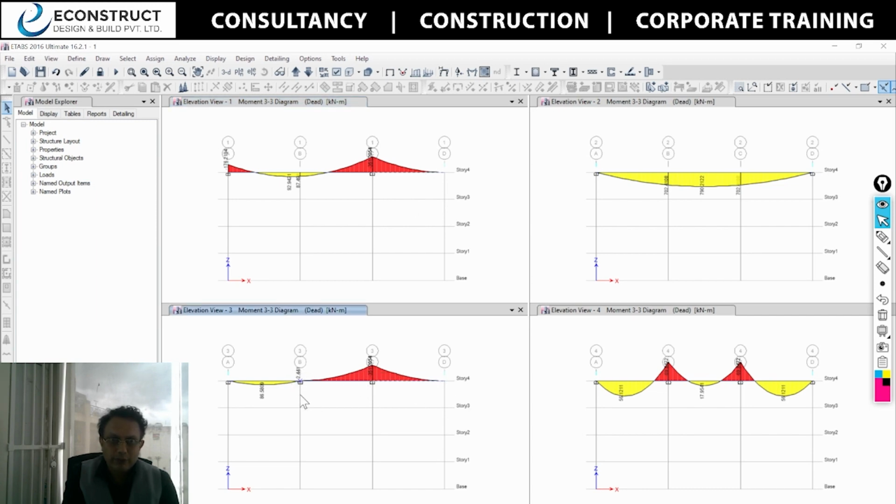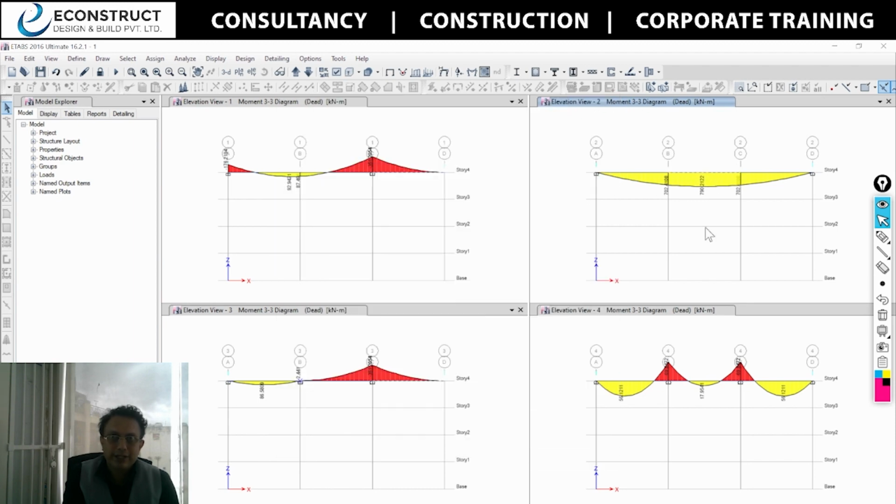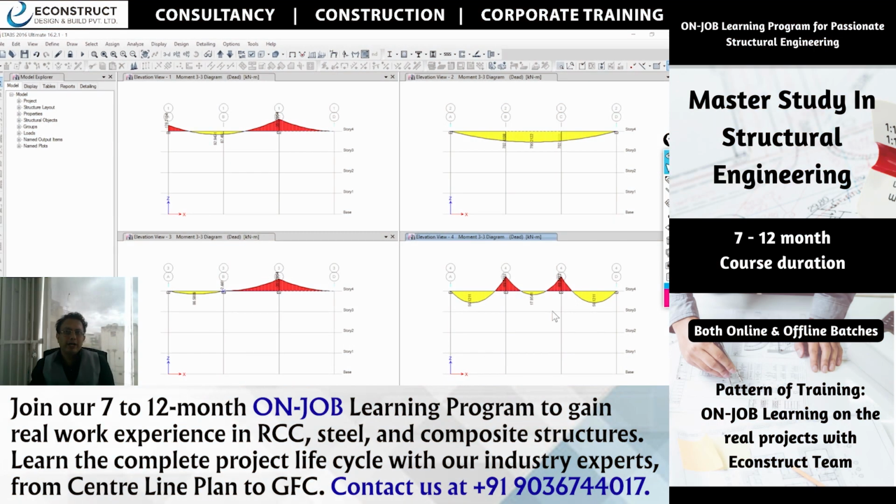Here I have given one support so that you can see that there are certain changes coming here. This is like WL square by 8. So obviously the center span bending moment will be higher. And this is the normal continuous beam with the pin support at the base.